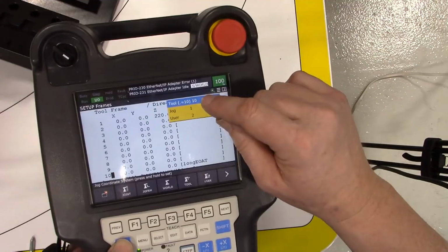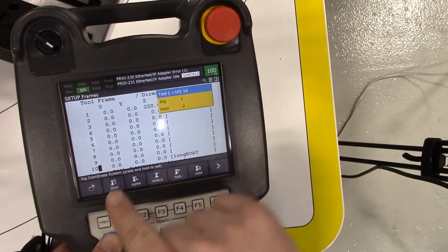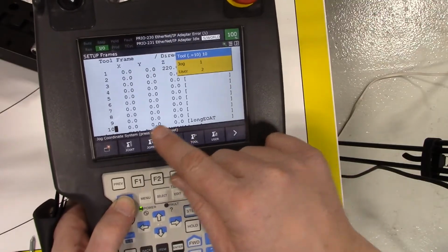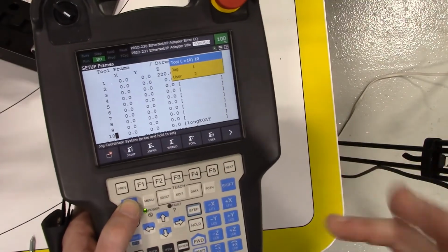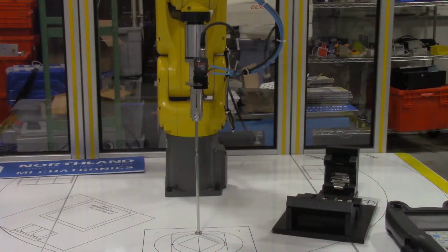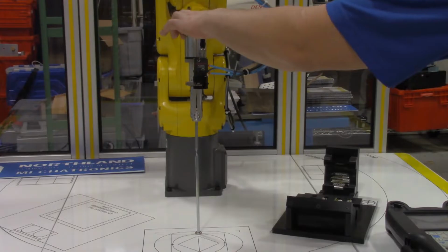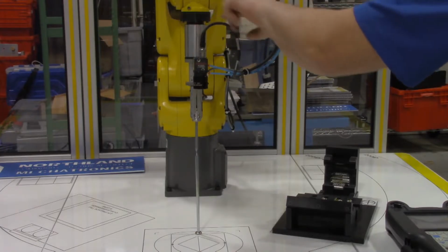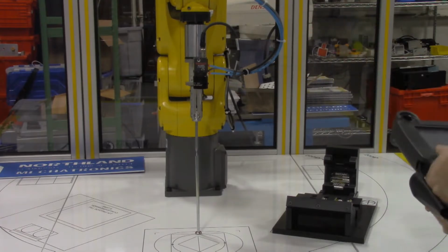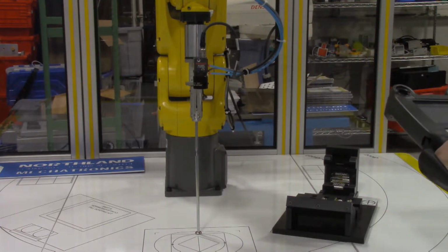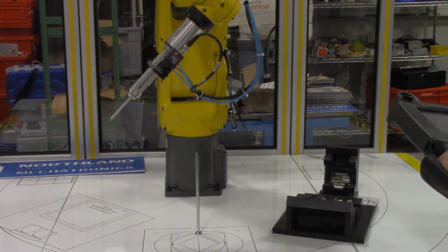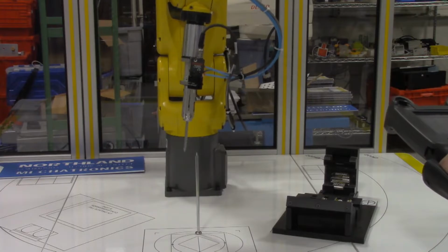There we go. So now the tool number is set to tool number 10, and you can see the parameters x, y, z for that tool center point are all zeros. So now this should have its tool center point be right at the end of arm tooling, the tooling plate, which is the black tooling plate located up here on the robot, and that's the 0, 0, 0 point for it. So if I were to jog this robot around now about the minor axes, you'd see that it changes the way it jogs completely.